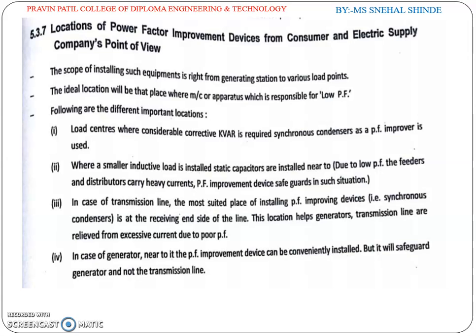Next is the location of the power factor improvement devices for the consumer and electric supply company point of view. The best location for the power factor correction equipment to be installed is where the apparatus or the equipment responsible for the low power factor is operating.